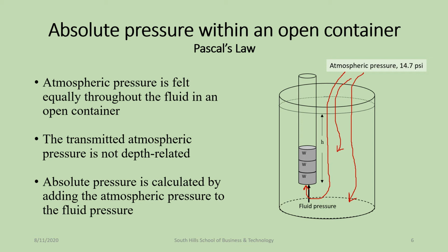However, it also means that this atmospheric pressure in the surrounding air is pushing down on top of this floating object. We're not going to take atmospheric pressure into account in this lab, because the atmospheric pressure pushing down on the object is offset by the atmospheric pressure pushing up on the bottom of the object. So it cancels itself out.